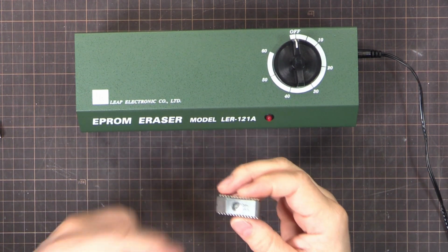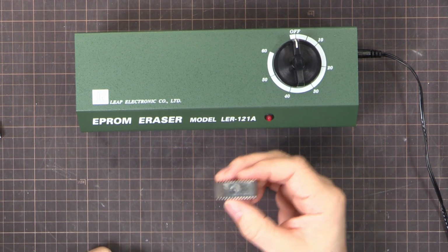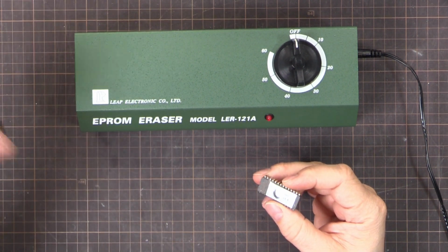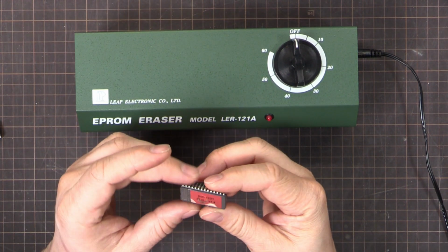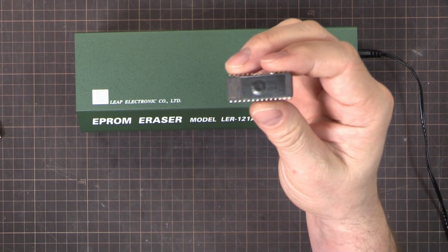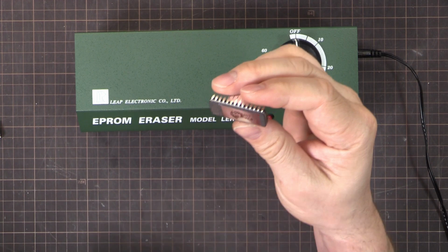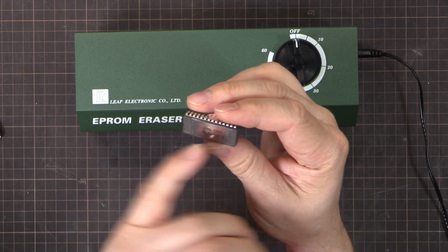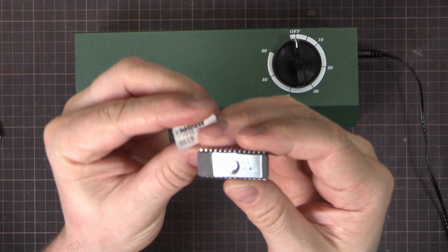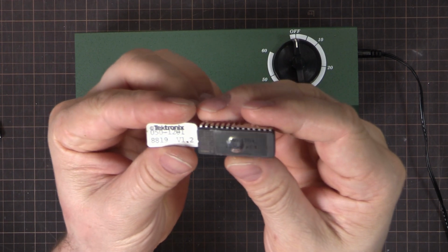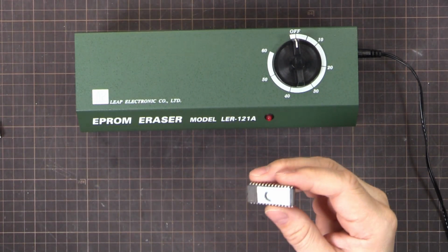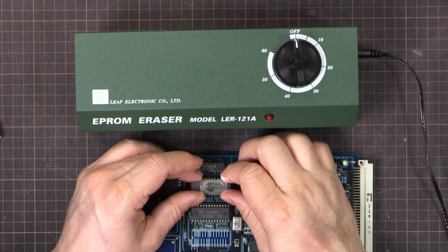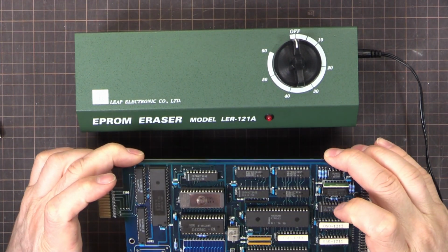And there's our chip all done. I just programmed it with that TL866 programmer like I mentioned before. I won't bother showing how to do it. If you need to know how to use that programmer, or if you've got your own, you probably know how to use it. Check out other videos online. I put a silver sticker on there from the label maker, with the part number 050-1201, the year and week 2236 and version 1.4 rather than version 1.2 on the Tektronix sticker. So all the information's there. Silver to try and reflect away the light, and we can stick that in there. Done. We have upgraded the firmware.